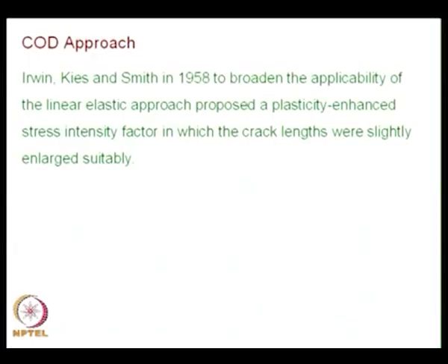What they said is, you have to get a plasticity enhanced stress intensity factor. In this, as we have already looked at in the context of surface cracks, instead of taking the crack length as a, they took a small extension of crack length which is dictated by the plastic deformation near the crack tip. This was one kind of approach.